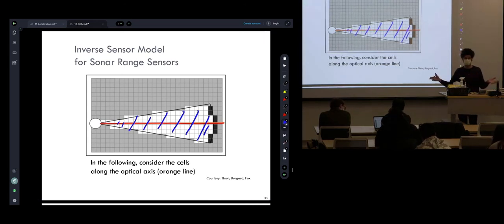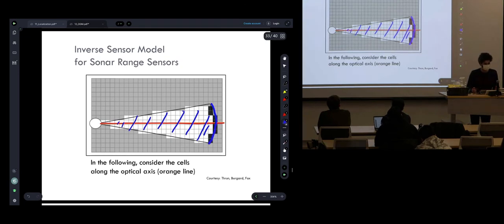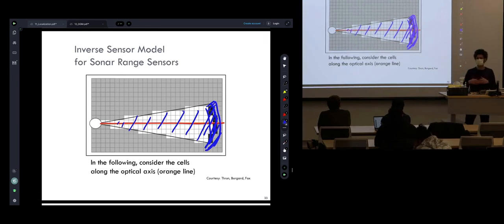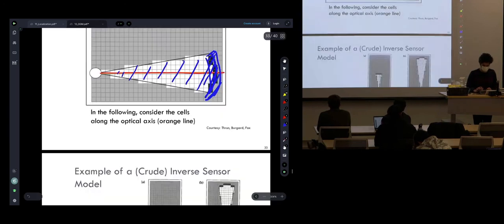Now, to what extent you want to make it thick like this depends on the problem, and you don't want to go too far because then it will make it inaccurate because now you're updating the map based on assumption, not data. So there is a trade-off. Likewise, for the end part, when you observe the obstacle, you can think about it as a point, or you might assume the obstacle has some sort of thickness, and maybe I am going to cover a little more area. And again, you don't want to do it too much because then you inflate the obstacle so much that it might not leave space for navigation. So in practice, you can expect to spend some time tuning these parameters, although there are good initial values in a lot of open source libraries already. They tend to give reasonable results out of the box.